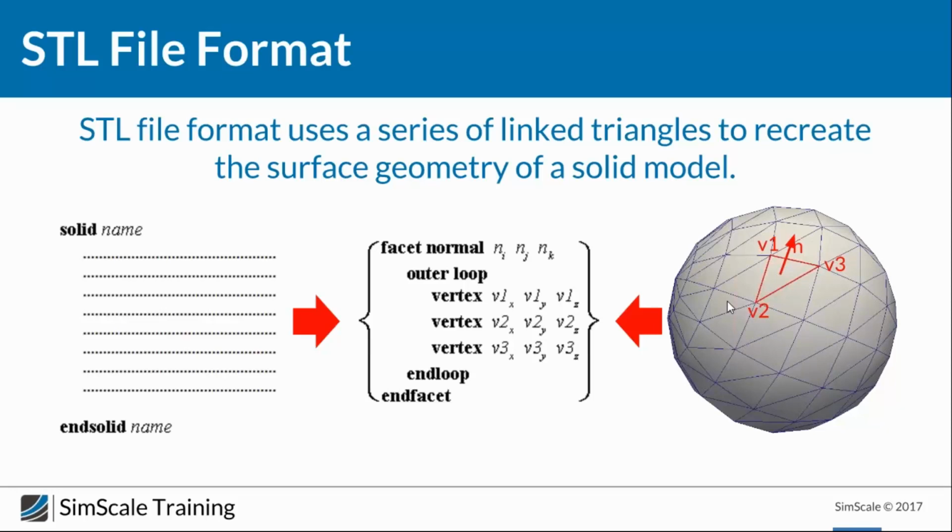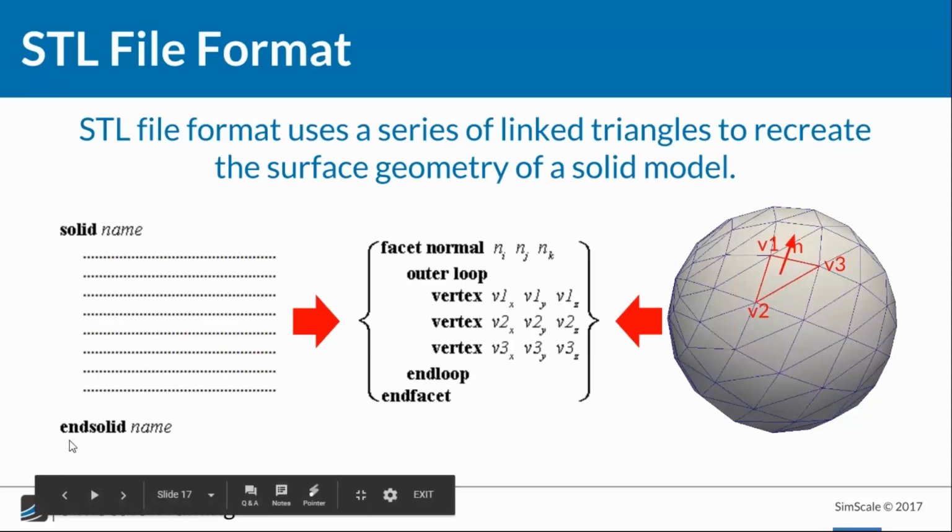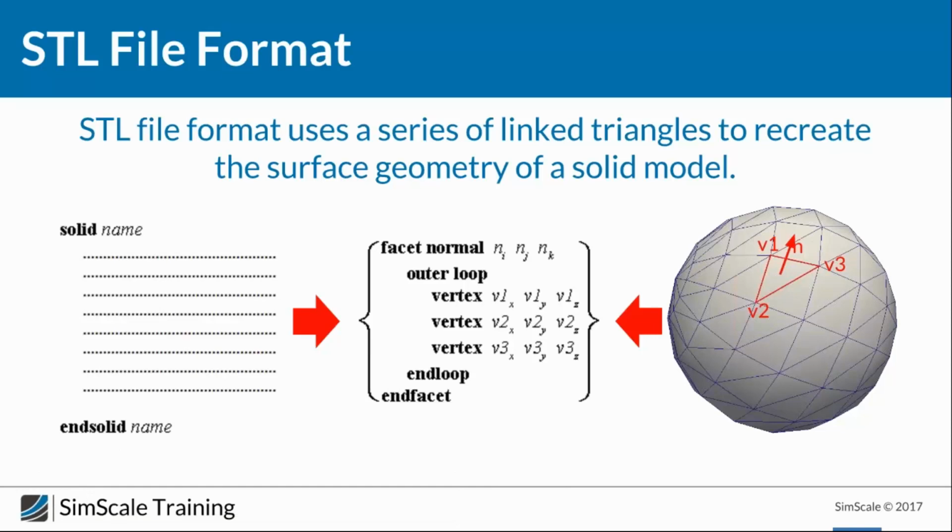And of course, if you want, for example, a multiple STL file with multiple solids, when you end this solid here, you will open a new one as a solid and you name it. For example, here we are talking about a Formula Student car, so we can name this one chassis, and then the next one will be solid, for example, tire, and we're going to start putting the coordinates for the three vertices of the triangle and the normals.